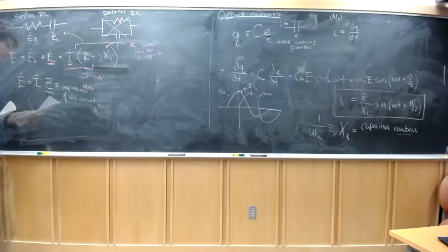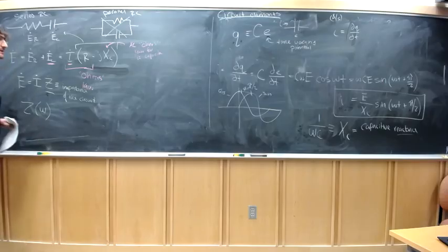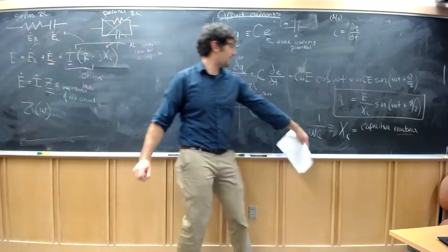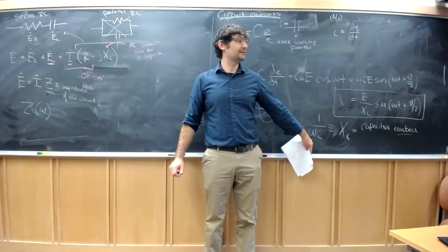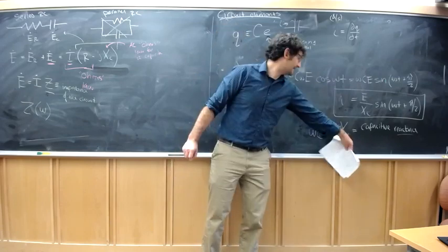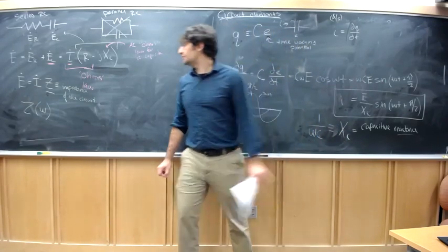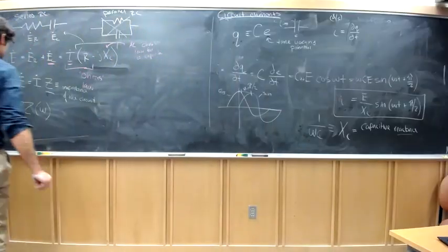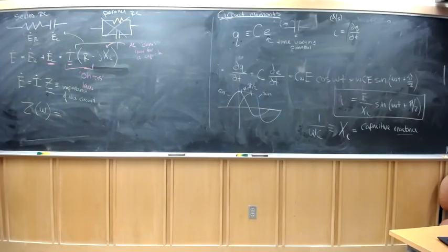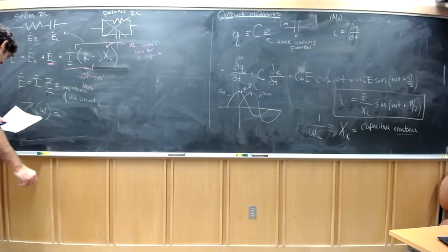But the problem is, in general, the impedance is a function of frequency, because it probably has some capacitances in it, right? And the reactance of the capacitor depends on frequency, right? So it's going to be frequency dependent, and it's also going to be a complex number, because there's going to be some phase shift between the applied sinusoidal voltage signal and the current response.